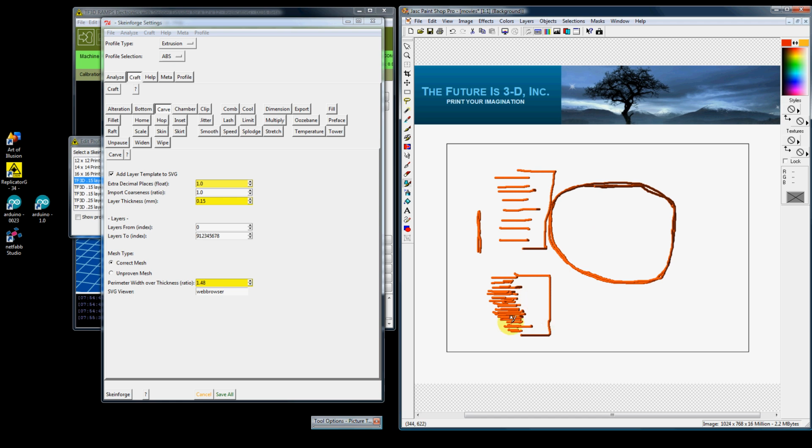So when you start getting lower in this layer thickness, you've got to start speeding up the print head. We've optimized these profiles, and you can experiment. Once our new print head is released, I'm hoping to get a lot faster speed, so you can do this. But Replicator G will choke if the G code file is too big. I'm hoping that in later releases they will fix that. You can only generate so many lines in Replicator G before it just stops.